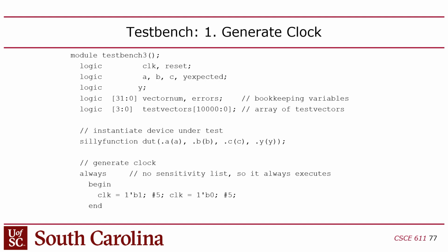Which is kind of weird because in a Cartesian coordinate system, it's actually switched. You've got x and y, where x is the width and y is the depth, right? But in linear algebra, it's swapped. You've got the vertical component, then the horizontal component, right? Okay, now in Verilog, they swap it. The width goes first, and the depth goes second.